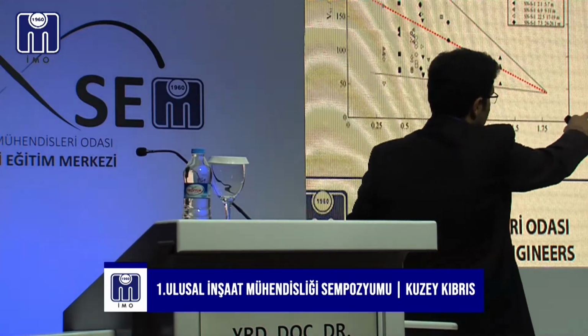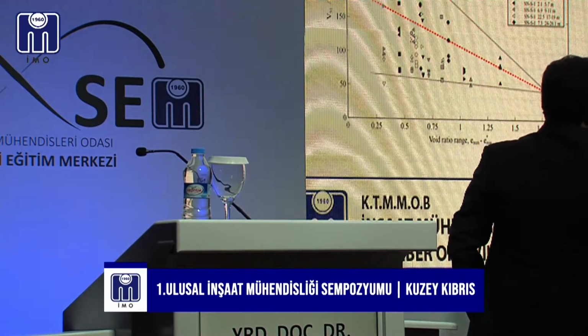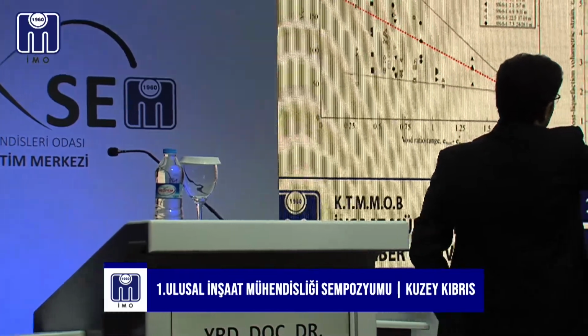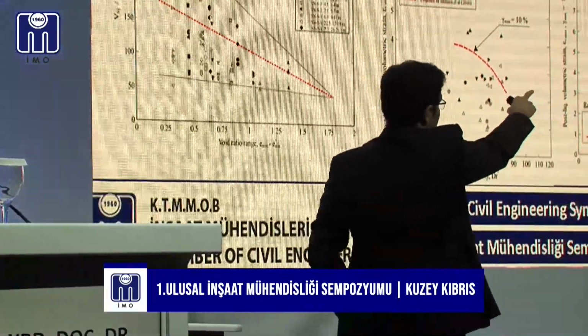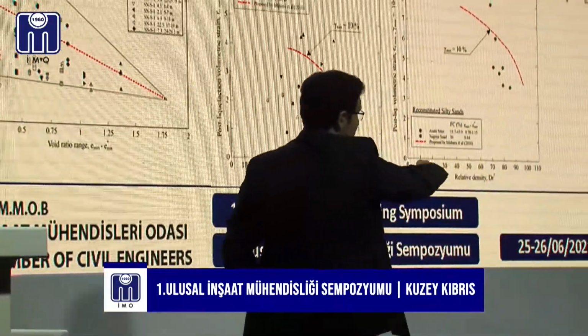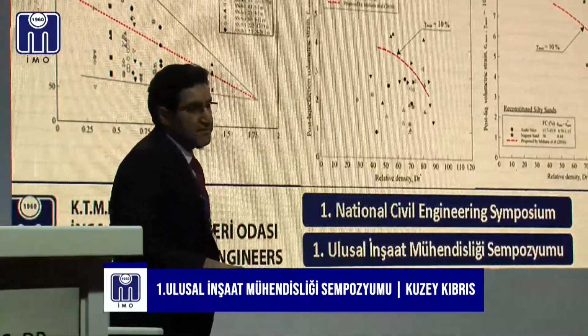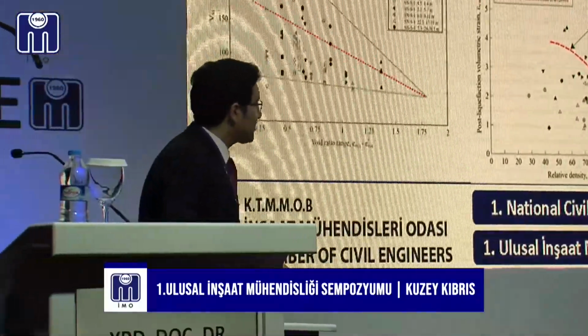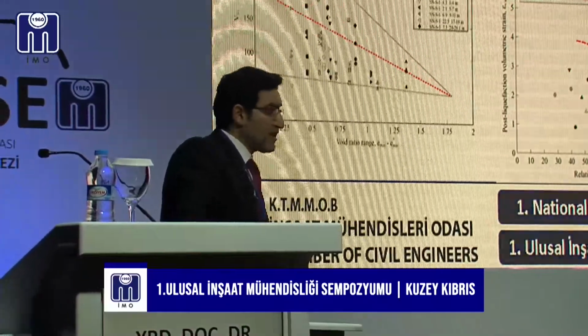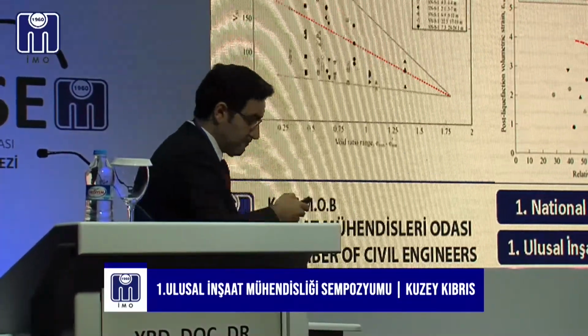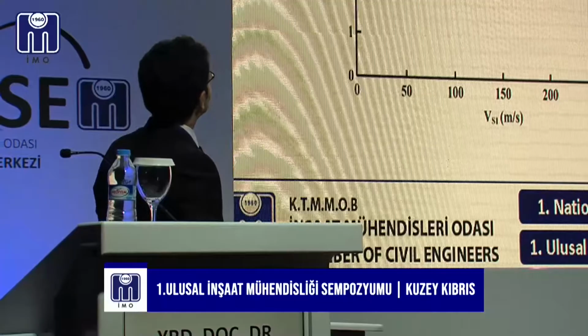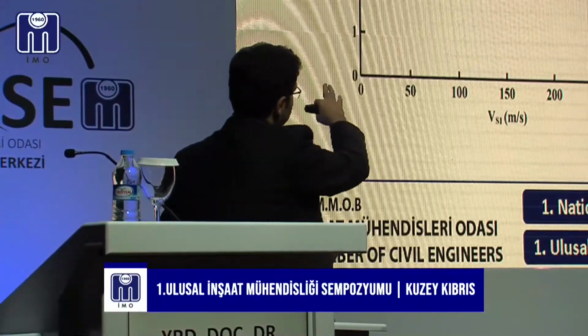Based on the relative density, we select one of these curves, and for that curve, we can find the corresponding post-liquefaction volumetric strain.